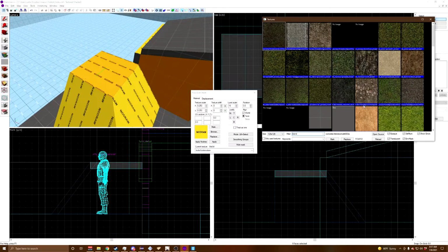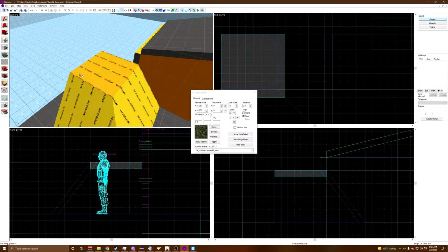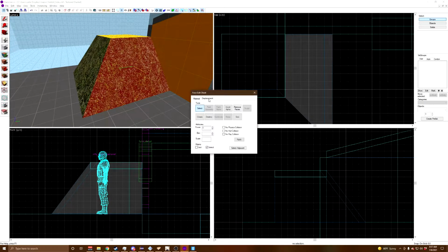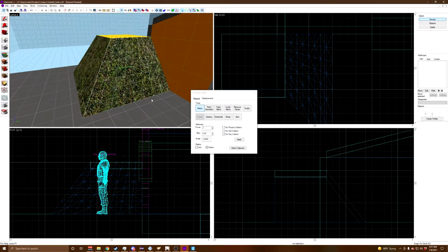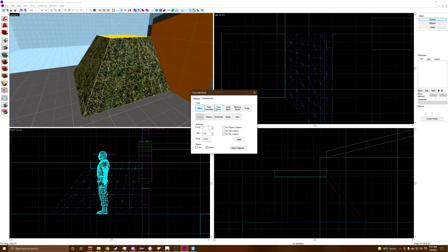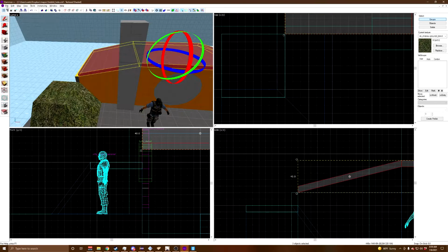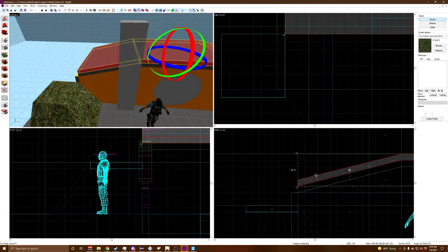Go ahead and find a blend texture that you like. You can do this by browsing textures and searching for blend. Blend textures are special because when a brush gets turned into a displacement, and that displacement has a blend texture on it, you can paint alpha within the displacement settings. This will allow you to paint between the two textures given in the blend. This allows you to make better and more realistic transitions from things like grass and dirt, rock and mud, stuff like that.